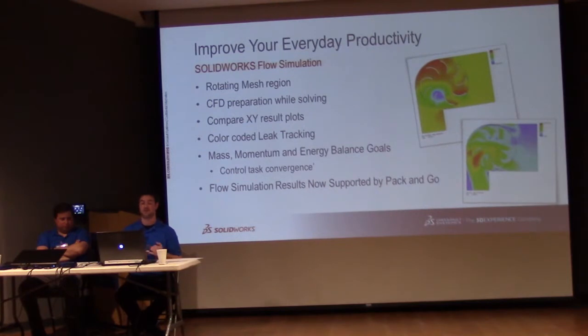And then also flow simulation results are now supported by Pack and Go. It's something I've been wanting for a very long time, especially when we're doing tech support with people. In the past, we had to do a Pack and Go of an assembly and then also send the results files, manually moving those results files into the zip folder. Now it's just a checkbox, just like the simulation results have been for a long time now.